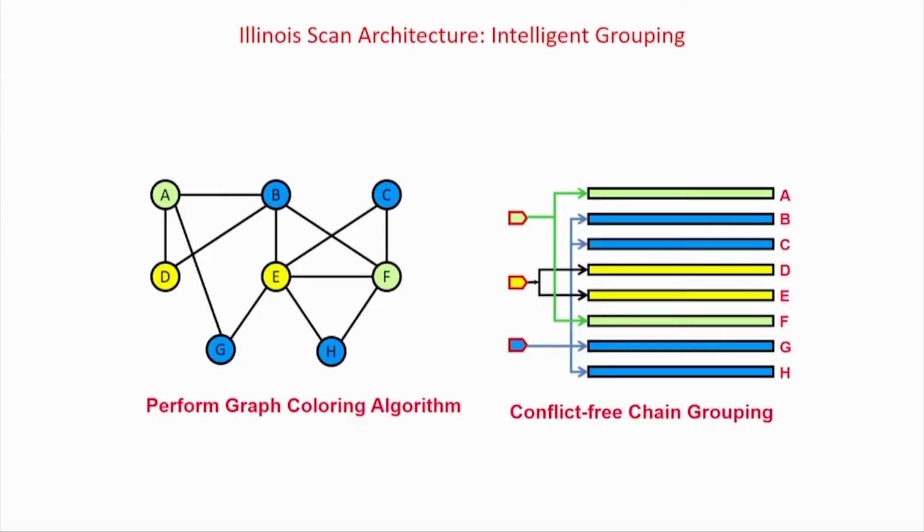But anyway, first we have seen scan, then partial scan, then how scans can be parallelized, and then how it can be optimized in terms of the number of input pins, as you should not have too many input and output pins for your scan. Still you should have parallelism, and at the same time you should not make faults untestable. So taking everything, it is an optimization problem which can be solved in this manner as a graph coloring problem. This mapping I have shown you. So this is one way of optimizing the scan, and as I told you, if I talk about DFT, scan plays the role of more than 99% of the area, or of your algorithms or space complexity, or the main heart of DFT is scan chains.